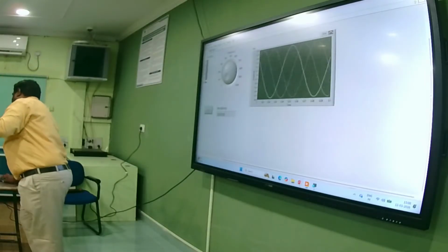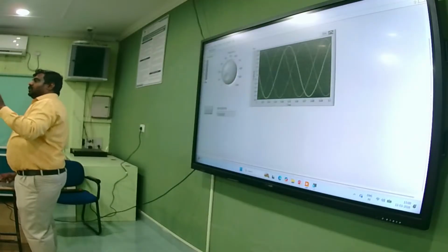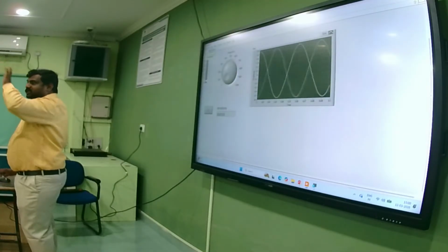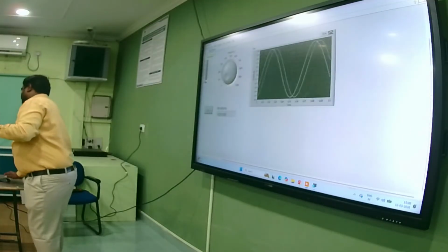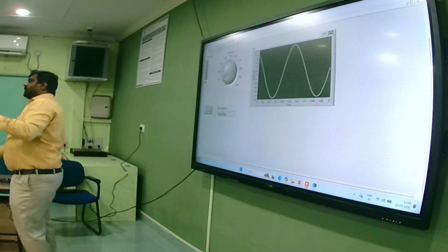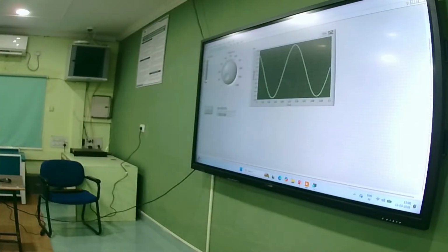See here. Click on the same run continuous button again. You are running continuous, so first stop running continuous. Make your code run one time. Then hit the stop button. Your code will stop. Am I clear? Whenever you are using loops, no run continuous button. Am I clear? Whenever you are using loops, no continuous button.